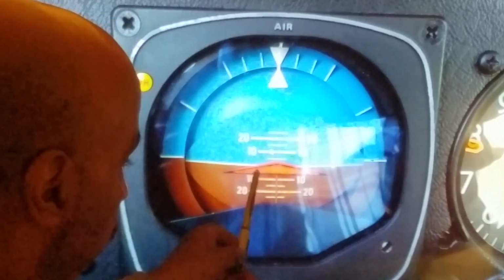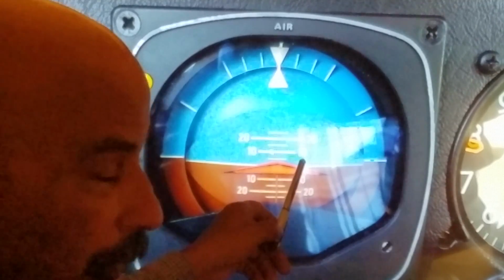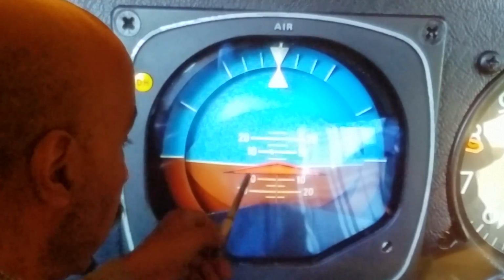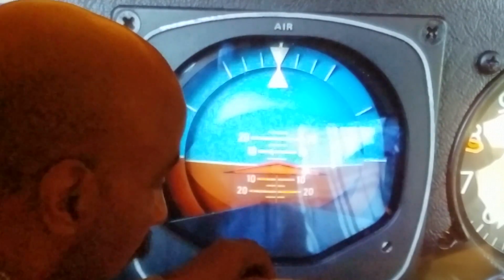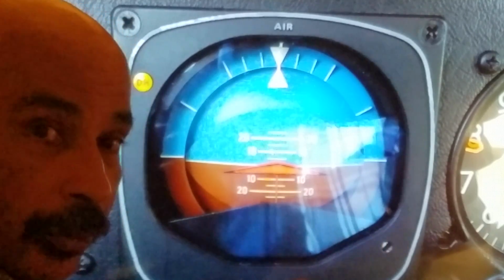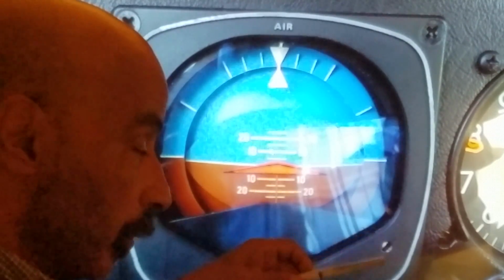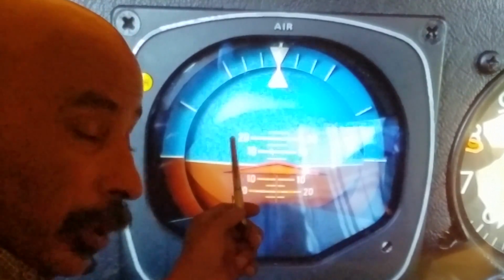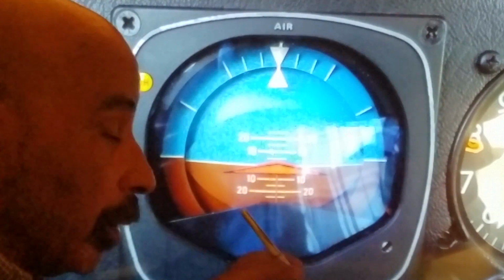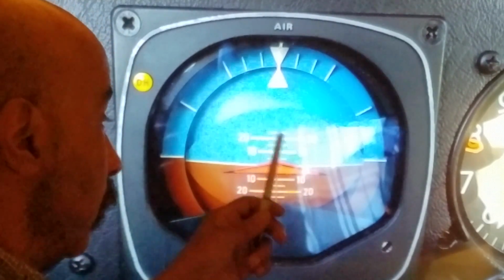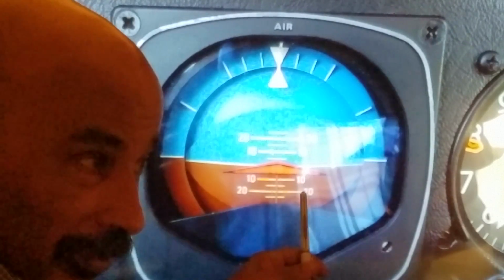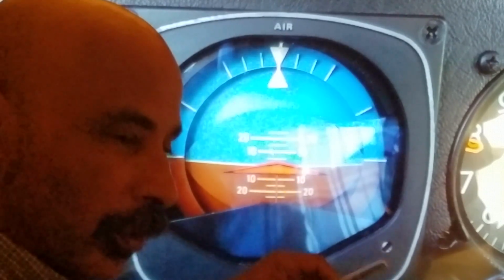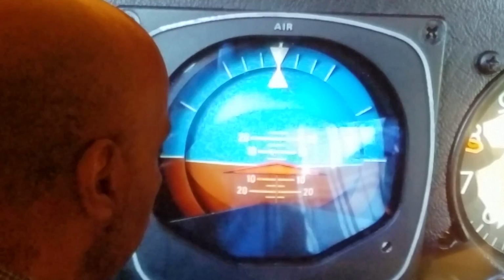The aircraft indicator or aircraft pictorial display here is the yellow triangle. The term attitude indicator is the most common term for this indicator on small aircraft like we're talking about. It's also called, again, the flight director. Sometimes it's called the ADI. So most times it's called artificial horizon, but attitude indicator is probably used 50-50 with artificial horizon in small aircraft.